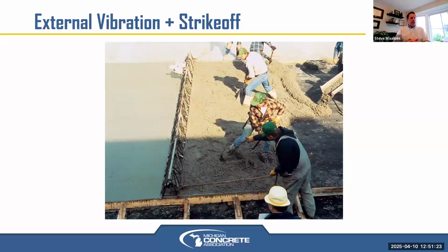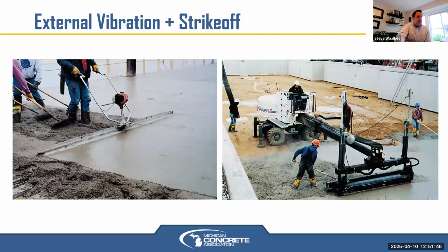The truss screed, a vibrating truss screed in this case, has an eccentric motor vibrating the whole thing to get some consolidation at the surface. It doesn't go very deep, so you might need some internal vibration on that, but it strikes off as well, again as the workers pull it along. Sometimes you'll see those still being used today.